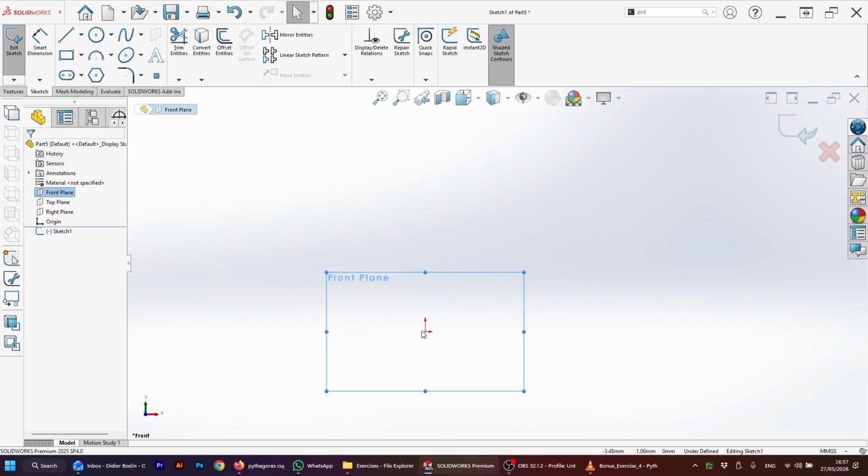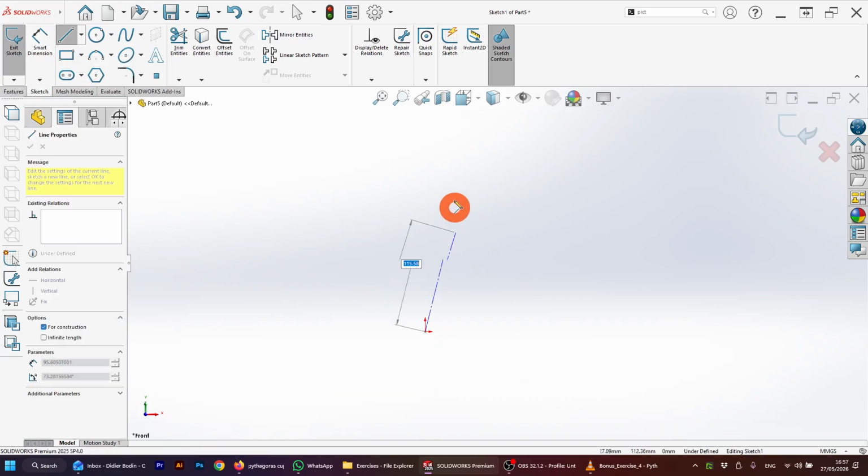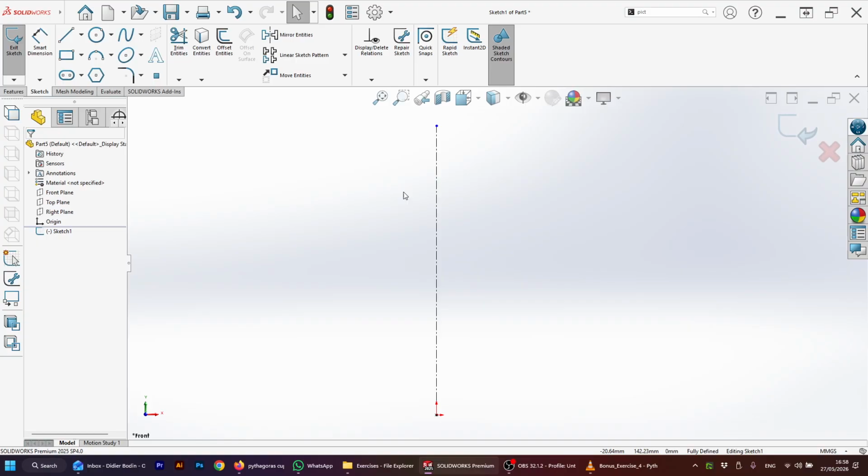I now open the sketch. You see, I can see the dot, I can see the two icons, sketch one of name of part. So the first thing I'm going to do, I'm going to place my axis, knowing that I'm using a circular function such as revolve. And now let's start to sketch.